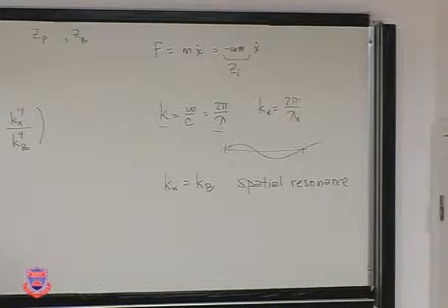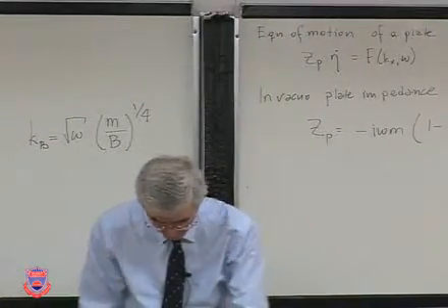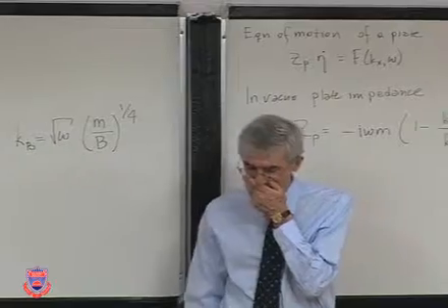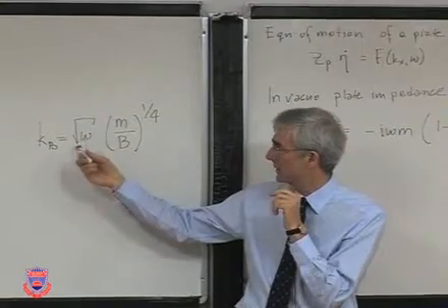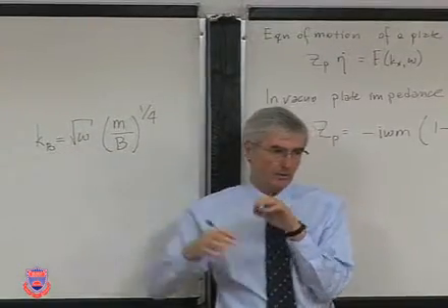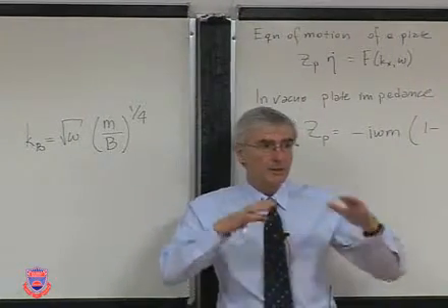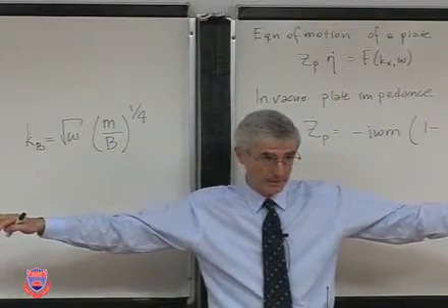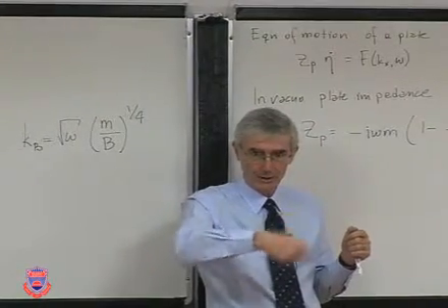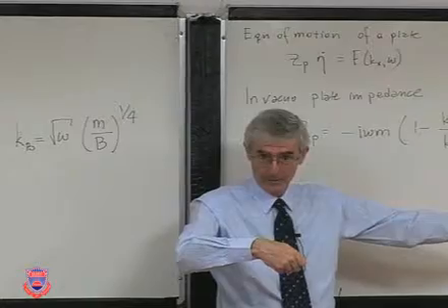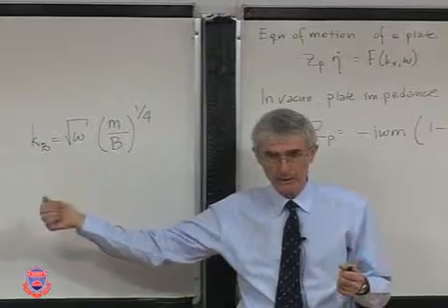Now, coming back to this for a moment. There's a relationship between frequency and bending wave number. If you're exciting a plate with a particular frequency, it has its own natural bending wavelength. When you have a string and you're shaking it at a frequency, it develops a particular wavelength. Similar in concept with the plate. There's a frequency and wavelength relationship.